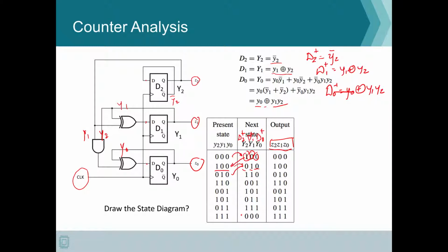So it goes to this state, and then we move this state in as our current state and recalculate with the equations. We compute that until we go into a loop. So here's our loop. If not all these states are possible, then we need to substitute those unused states, and then we should also be able to do our state diagram.